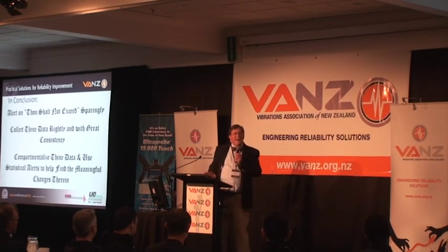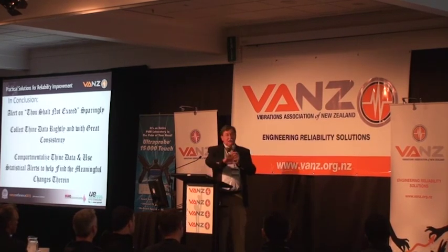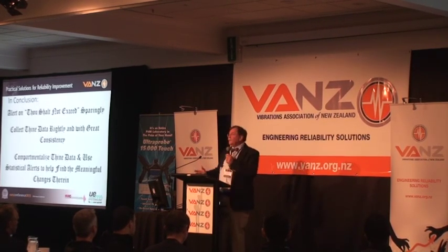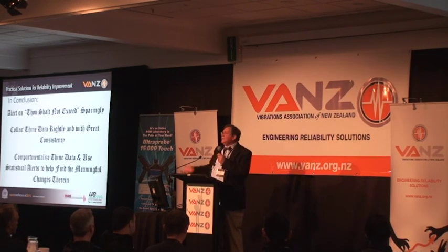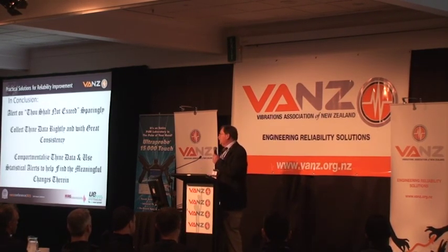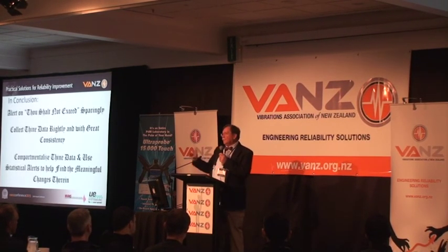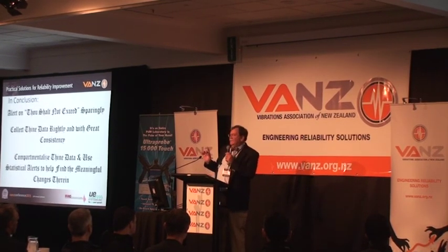So what ended up happening, and we discovered during that refueling outage when I arrived on scene, had nothing to do with me being there because this was already underway. When they opened it up, they saw that, sure enough, one blade over here was gone, two blades over here were gone. They started looking and they opened up all the hoods and they looked at all the turbines, and there was a pretty consistent manufacturing defect at the blade root.